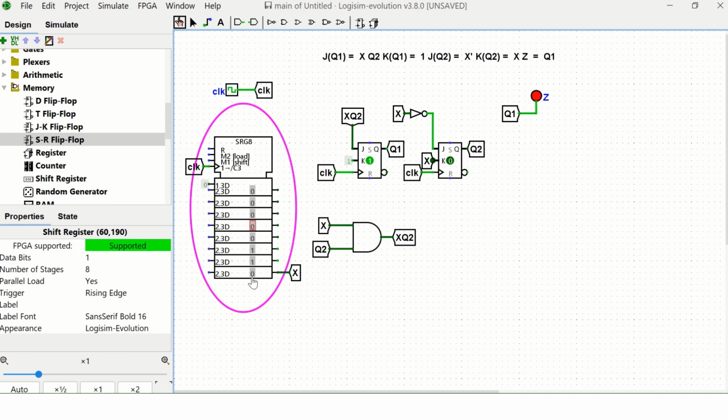Here I have 1, and then 0, 0, 1. This should be on. Here 1, 0. No light should be on. So you see the idea is that when I have 0, 1, so here X is 0. Now it's 1. So the sequence is detected.